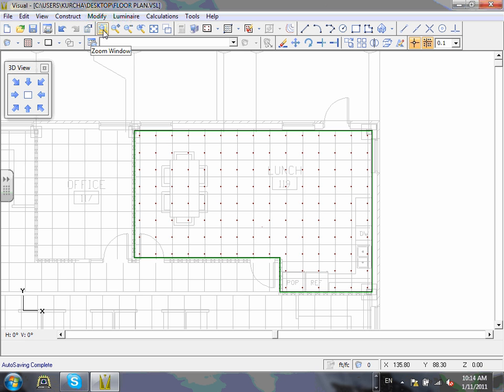It says Lithonia. I know it's a Lithonia fixture because this book has multiple manufacturers grouped together in it. So first of all, it's a Lithonia commercial and industrial fluorescent. That's the family that we're looking for. Then the type is GT8. Very important. The group of the fixture is this group, and then the family type is GT8.